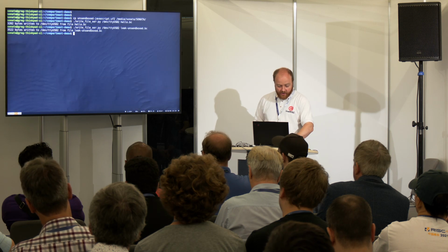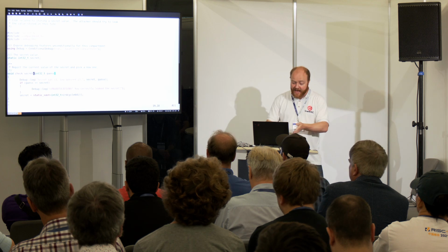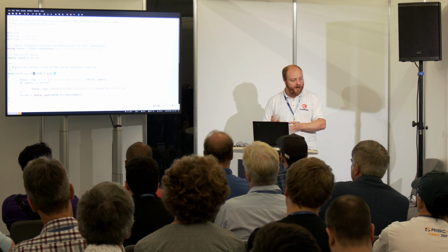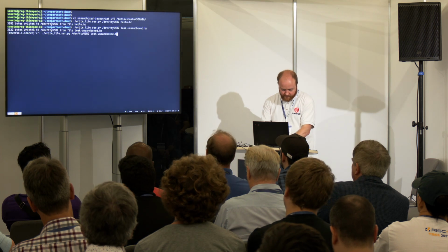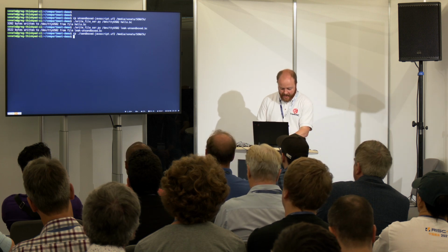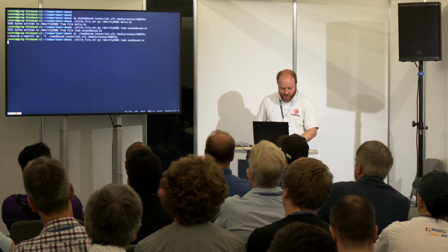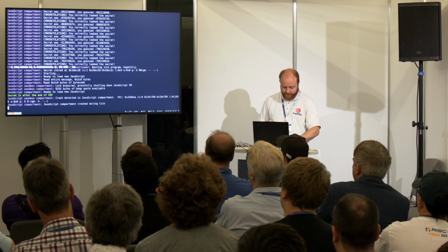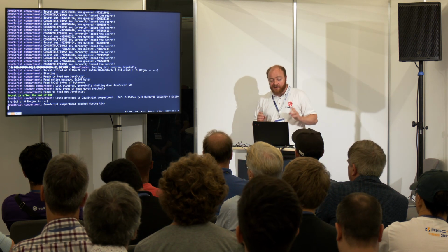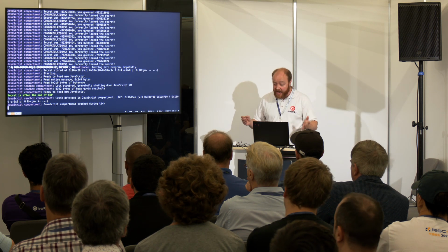So that brings us on to CHERIoT compartmentalization. Here, we rebuild the software, but we do it a bit differently. Now this piece of code, this secret, lives in its own compartment, in a different compartment from the JavaScript interpreter. I'll load that onto the board. And then we will, oh, wrong command. We're now going to try and run the attack again. And it doesn't succeed. The JavaScript compartment crashes. It attempts to access the memory address, but it physically cannot. The CPU will not let it because of the CHERIoT capability checking, and it just can't get at that secret.